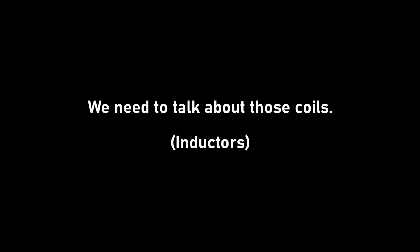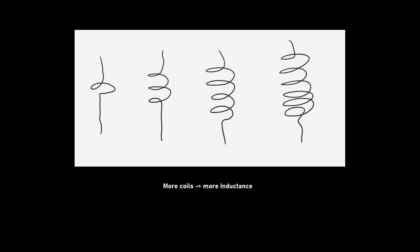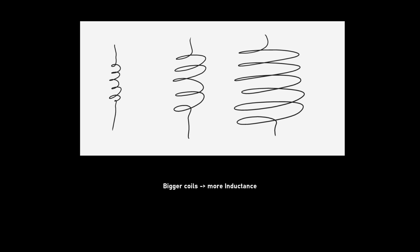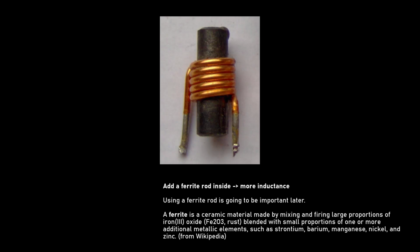A couple of points we should make about what's going on here. These coils are called inductors, and it's a very simple electric component. And they're called inductors because, of course, they induce a current. Now, how much an inductor can do its job is measured by something called its inductance. And we can control the amount of inductance by changing the number of coils. We could have one coil or many coils. We could increase the size of the coils. We could put something within the coil, like something called a ferrite rod.